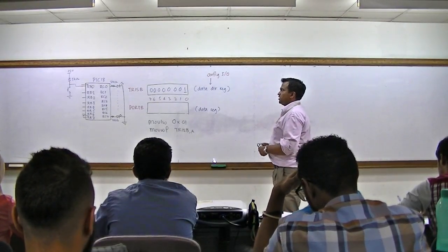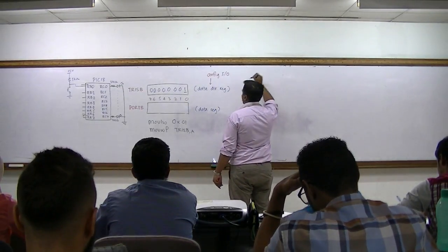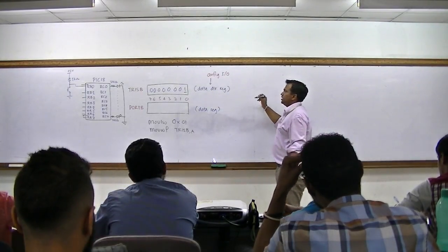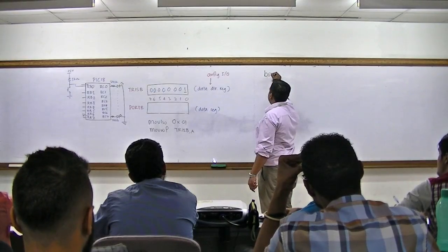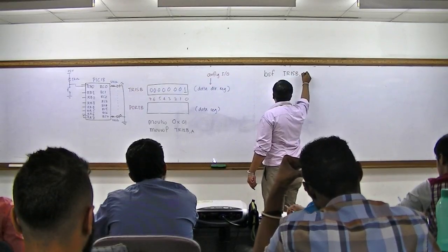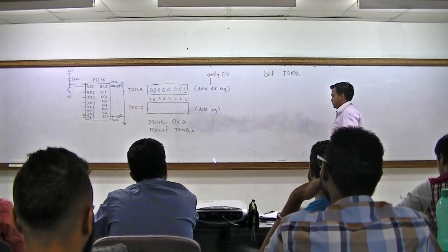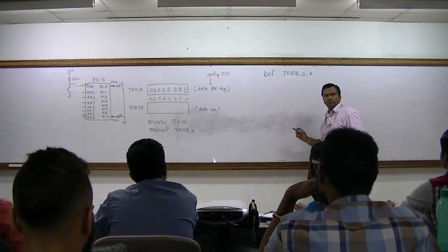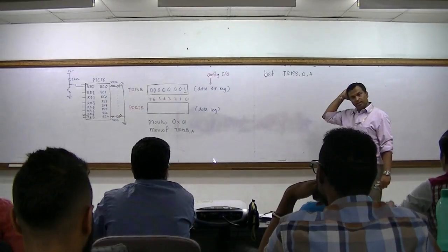So what should we do to this B? FF. But because we're just dealing with one input, I can also configure just that one bit. So I can use bit set F to this B pin number 0. So I'm configuring port B pin number 0 as input.